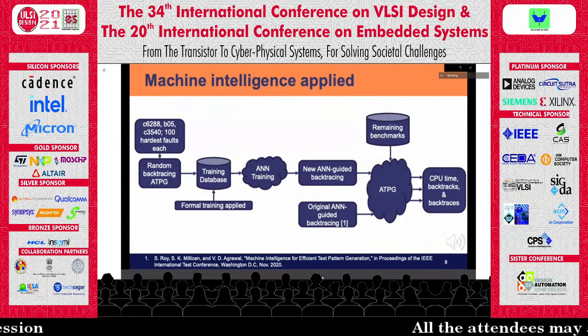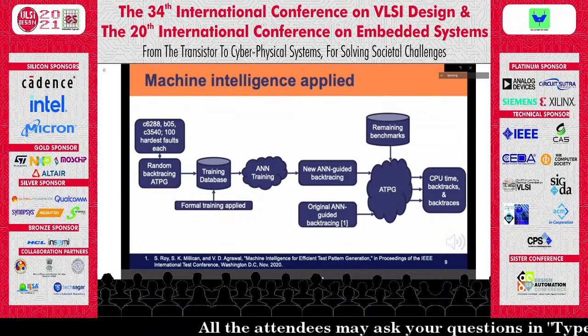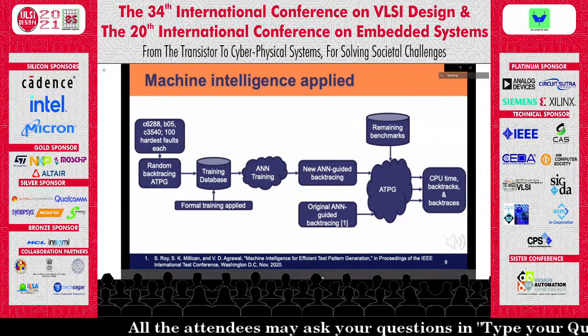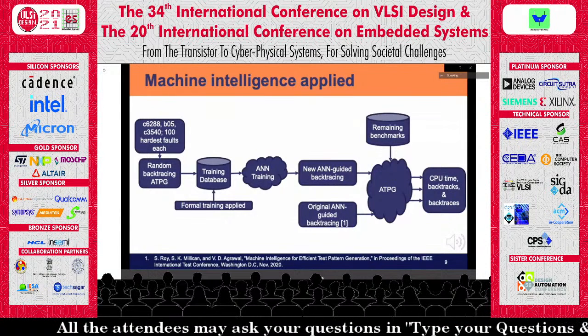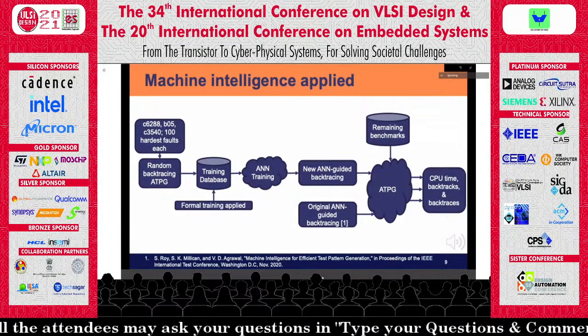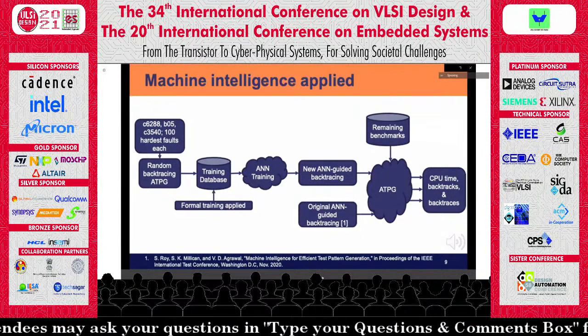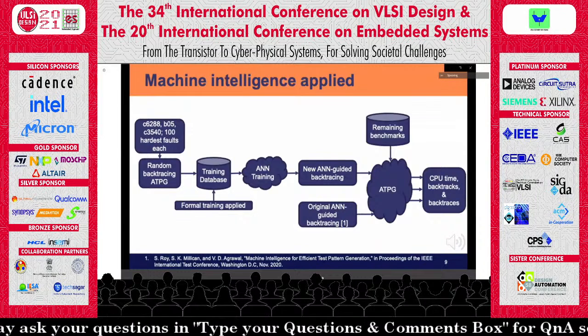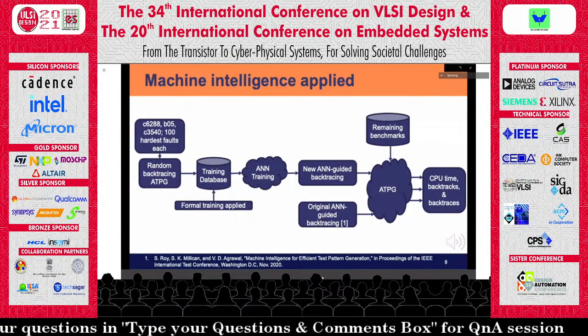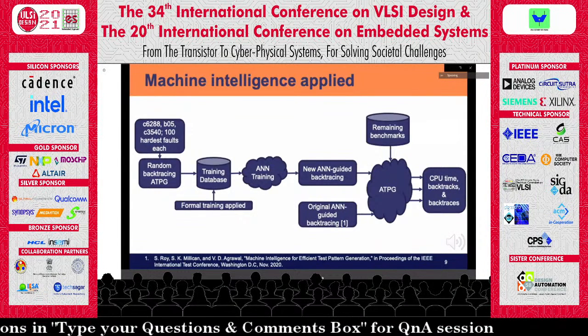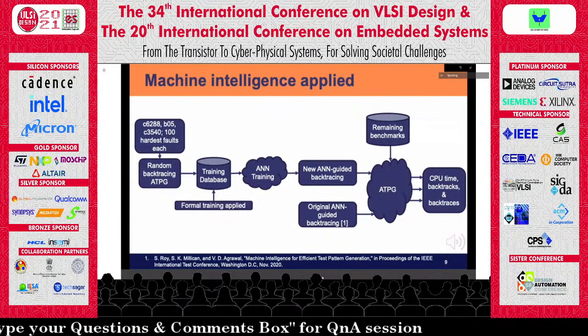The ANN training in the ITC research study was ad hoc and rudimentary. Therefore, this study provides a formal training that may elevate ANN-guided PODEM's performance. This study examines such a training method. The training recursively uses ATPG data generated from hardest to detect as well as easily testable faults, resolves conflicts in data patterns, for example when different ANN outputs come from similar inputs, and discards data that does not improve the guidance of the ANN.